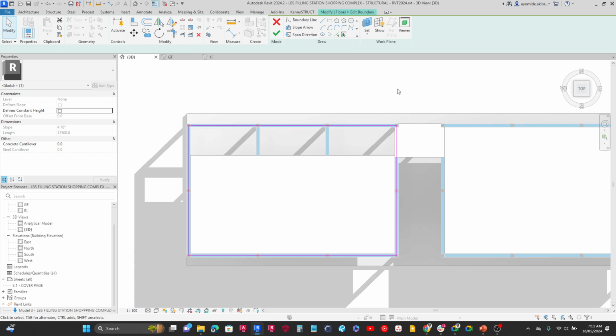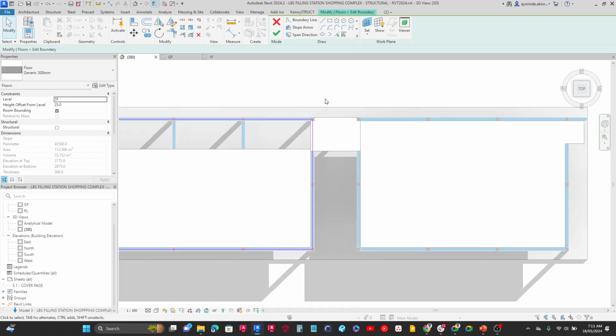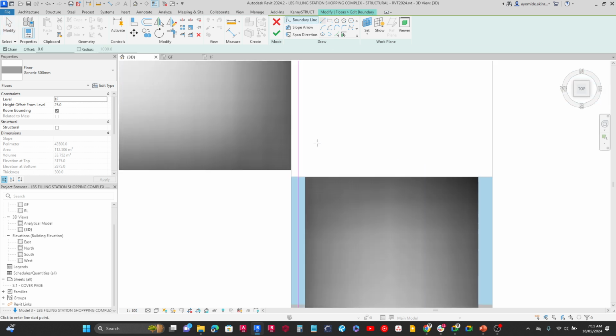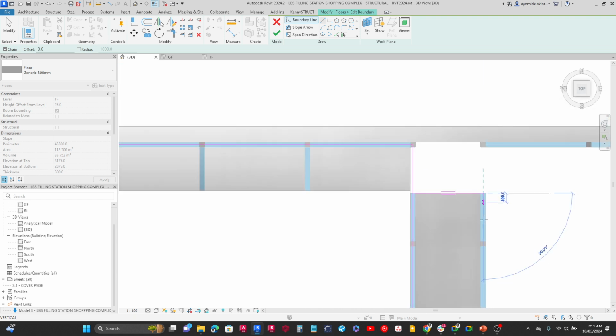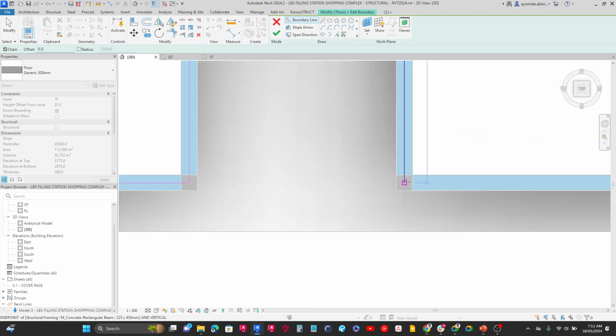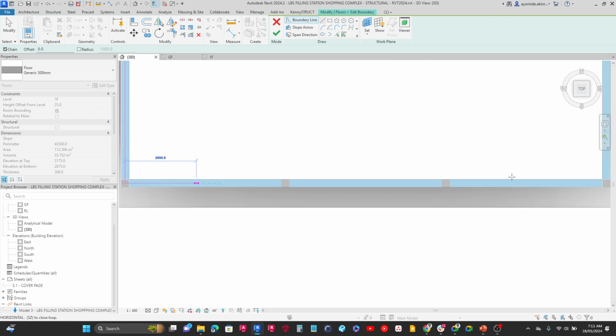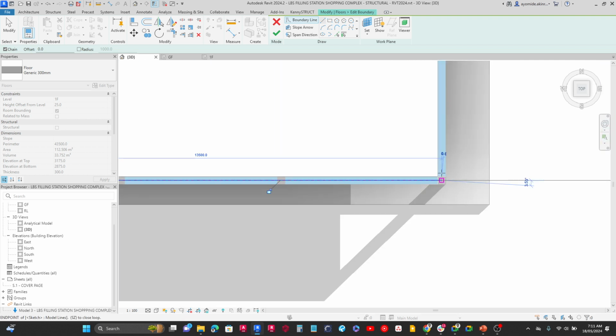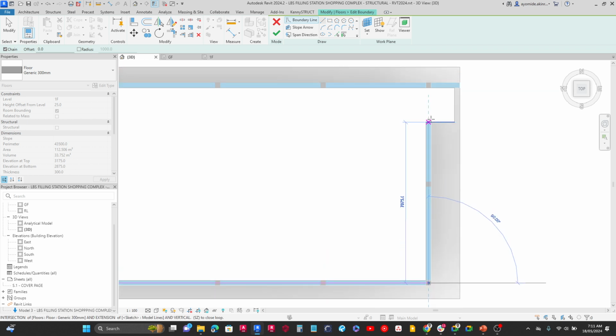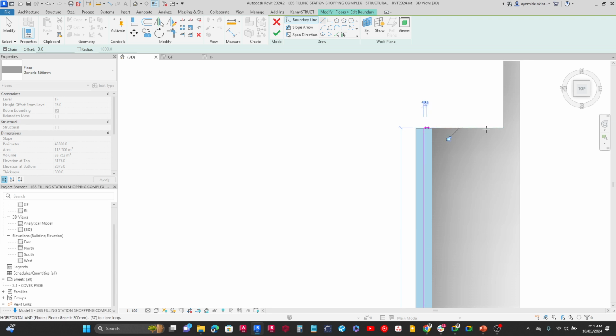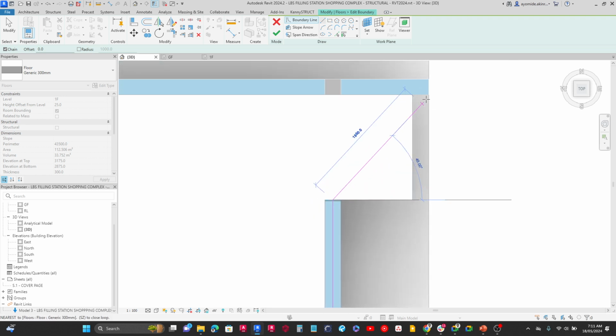And because I want it to be one full slab, I'm going to use my line command. So click at the top here to draw more. I'm going to click here, from here to here, come over here, click here. I'm going to click here to draw one here. Let's go over here and draw another one from here. I'm going to draw one for this slab, and we want this slab here to be at exactly this beam here, so the edge of the beam.